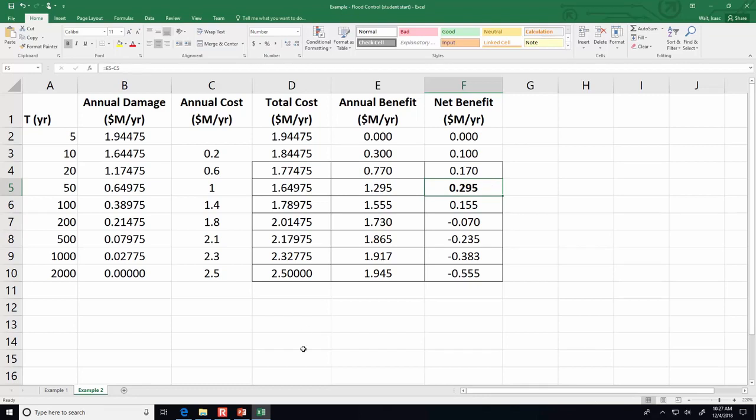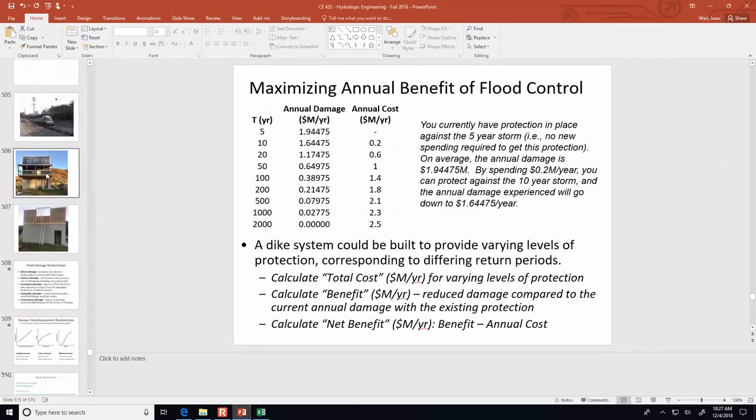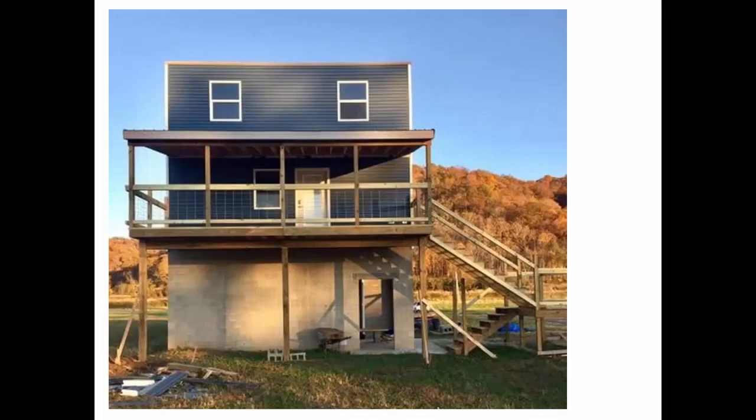Okay, well, one last thing I wanted to show you was some pictures that Ashton provided me with of that tiny house that's being built out on Route 2. So this approach to avoiding damage is just that you figure how high the water is going to be, and you make that lower level of the structure unoccupied space. That's maybe where tools or cars or vehicles are, and then it's only the upper part of the structure that's going to be inhabited. And I wish you could get a sense of how small this actually is. It maybe doesn't seem small, but you kind of get a feel for it.